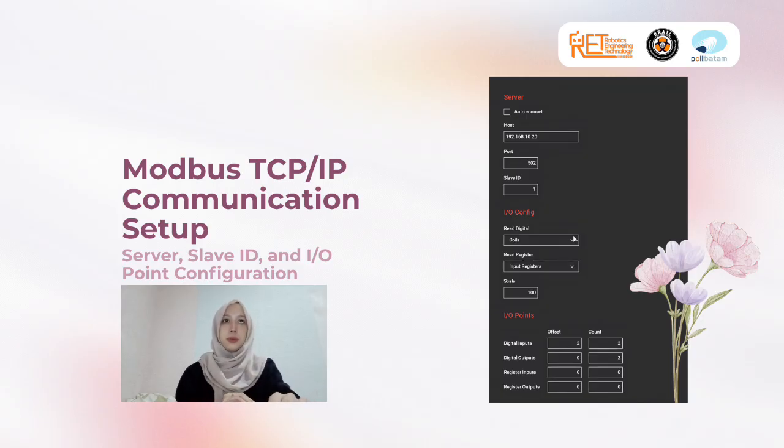The second one is why I chose coils instead of discrete inputs, because coils can read the sensor states into the PLC's memory, and also read the actuator commands back, whereas discrete inputs are read only, so they wouldn't let Factory I/O push sensor data in at all.